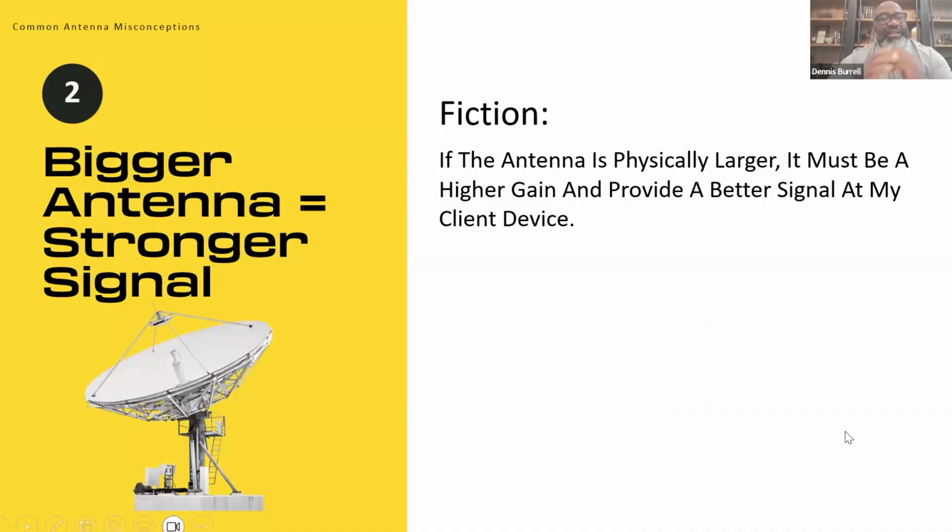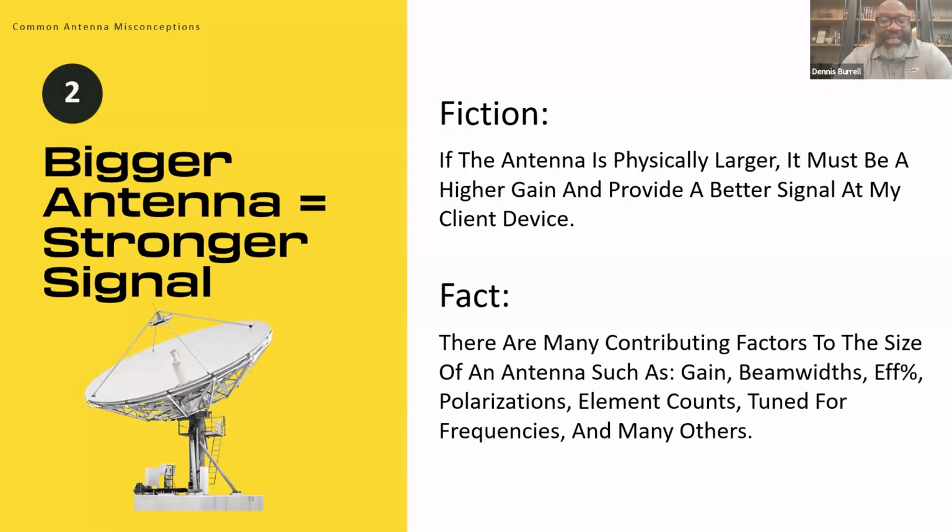A bigger antenna equals a stronger signal. If the antenna is physically larger, it must be a higher gain and provide a better signal at my client device. That's fiction. In fact, there are many contributing factors to the size of an antenna, such as gain, beam width, efficiency, the polarization, the element counts, how it's tuned for frequency, and many others.